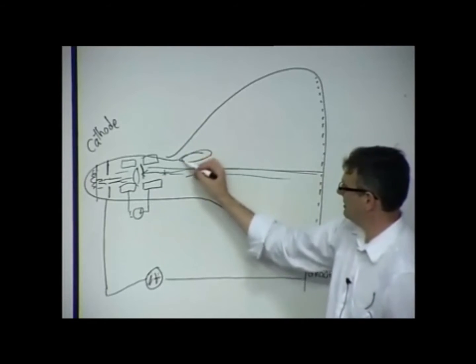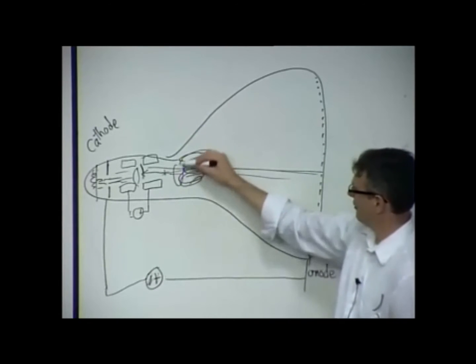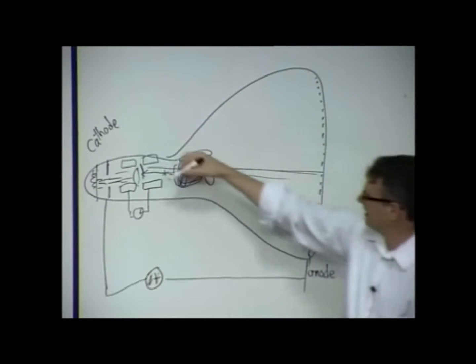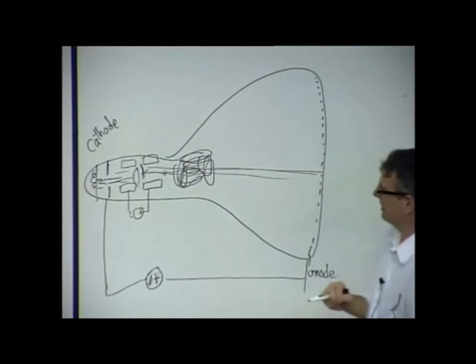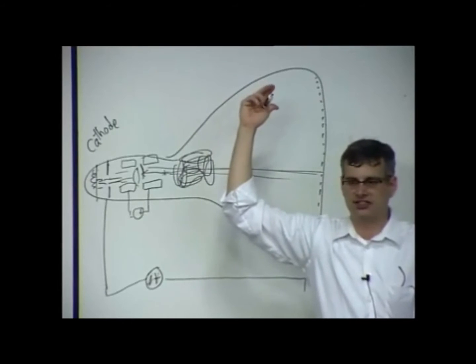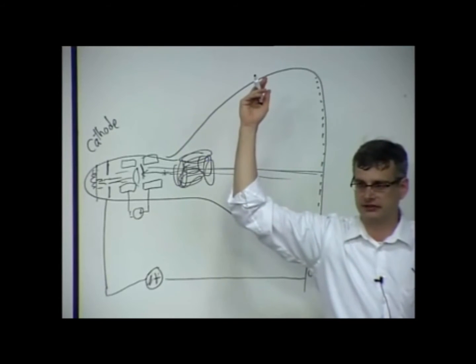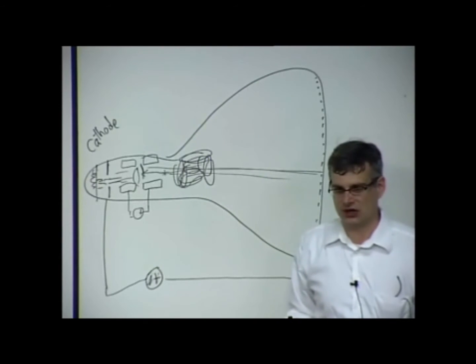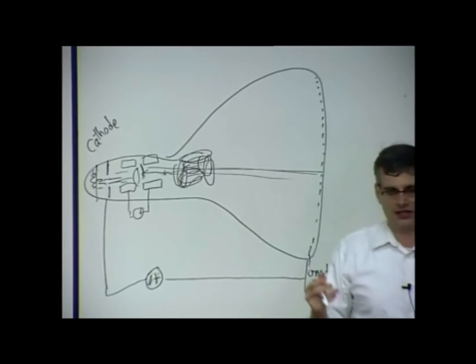And of course, there are some steering magnets here, both in the vertical and horizontal dimension, and that causes the beam to sweep around. This little plate you can modulate with a data signal to control the intensity of the beam, and voila! You have black and white television. State of the art for the 1940s, right? And so I would teach this. And of course, back then they were still using CRTs in 2003. And the students were so happy.